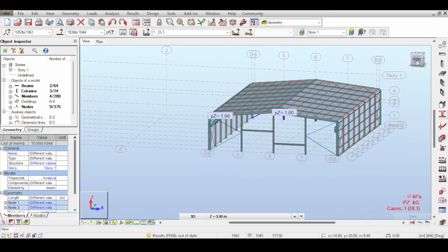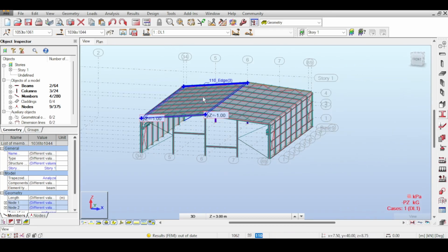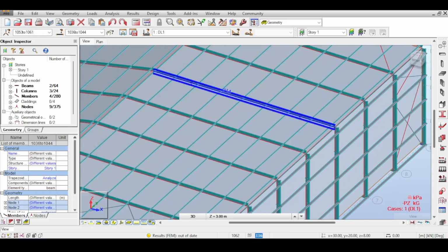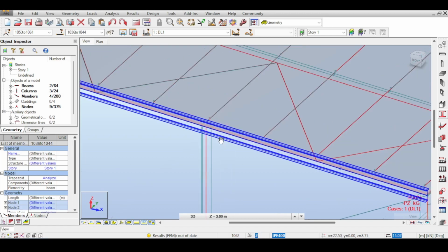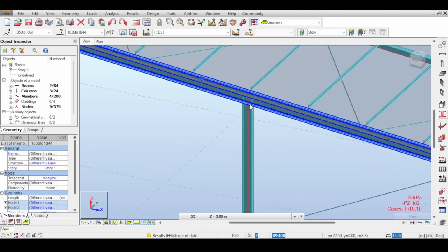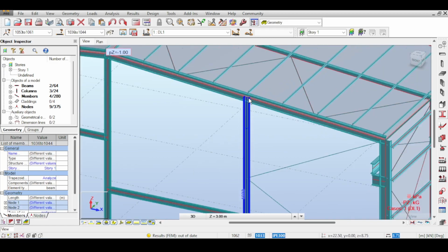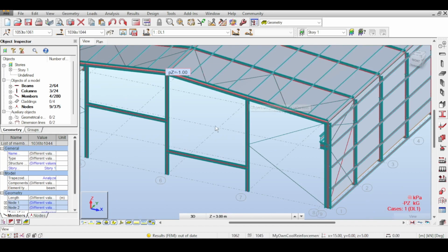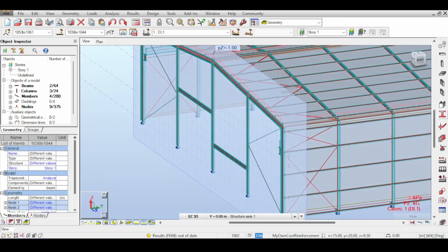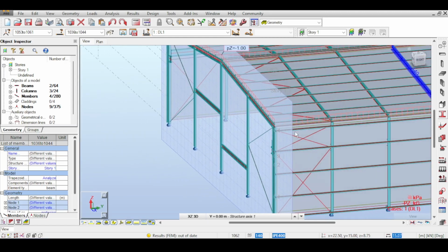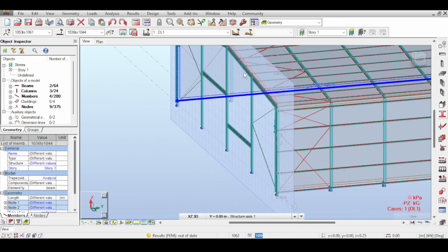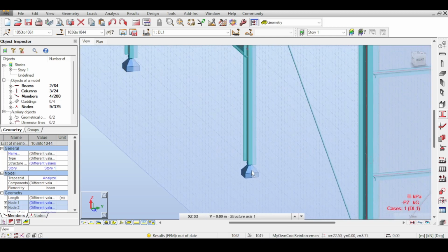I mean, I still have to do the wind loads and combinations, but I'm unhappy still. Why am I unhappy? Because the bracings here are not bracing the positions where the gable column is attached. Why is this relevant? Because those points are going to feel the force of the wind load. If you have wind load here, which is pressuring on this plane, you know how the wind load is going to be distributed. The entire gable frame will carry the wind load, and of course, it's touching basically the portal frame on top and the support on the bottom.